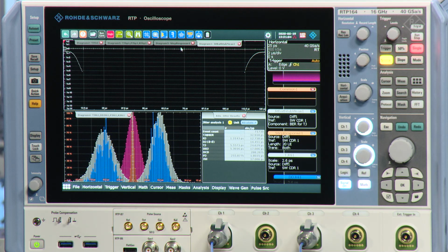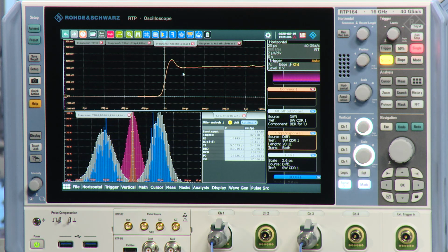Now I go to the next tab where I rearranged something which is new. I introduced the step response as an important measure for the channel measurement. So this gives an estimation about the channel from the DUT, from the chip, via the domain controller, via the baseboard, the compliance baseboard, and the cabling. You see that there's kind of ringing, which is typically introduced by the press-fit connector of the PCI Express edge connector.